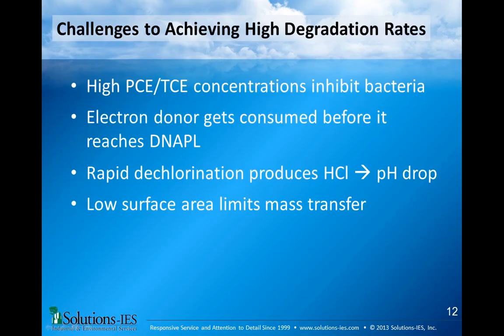As you look here, at a Damköhler number of 0.1, that's really no enhancement. A Damköhler number of 1 gets you a 1.5 improvement. But if you can go up to a Damköhler number of 10, now you've got a 3-fold improvement. At 100, you've got a 10-fold improvement.